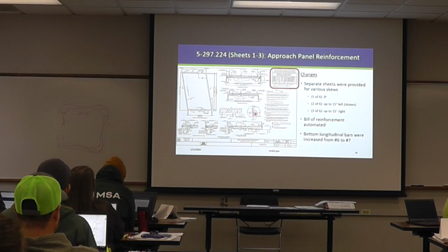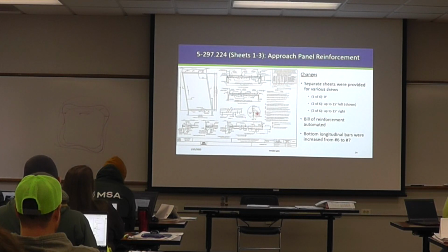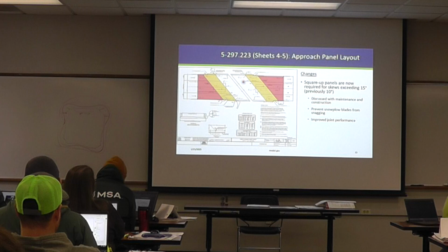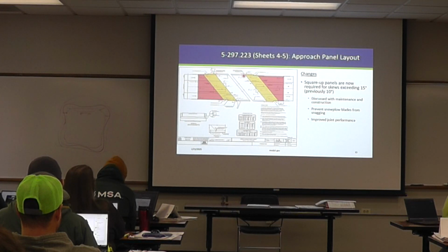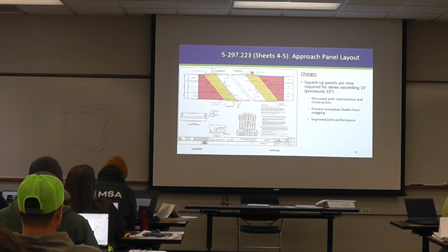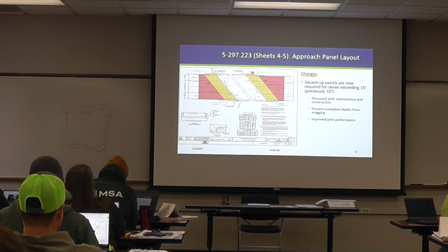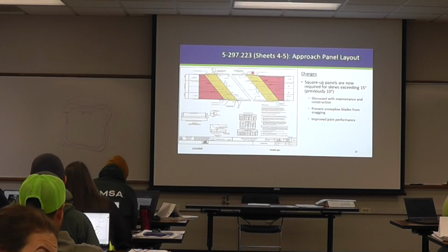So there is that polystyrene between the wing wall and the approach. Great, okay. And that's really just where you've got these parallel wing walls, right? You wouldn't have to have it for a flared wing wall. Yeah. For the parallel ones, we're just running along. I was on bridge for a little bit of that. Had that on one side, but completely different on the other side, on the same end of the bridge.